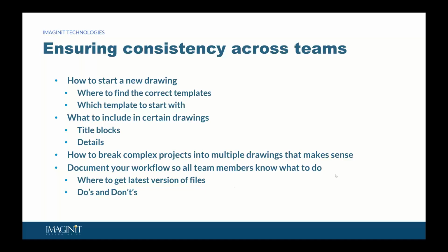And some of the other do's and don'ts. If you are creating complex surfaces, are you going to be data referencing them into other pieces? If you create a surface from an XML, you can't delete the XML file because the surface will no longer rebuild. If you're using data shortcuts, again, this comes back to the first one. Make sure your file directory structure supports the data shortcuts well. If it's too deep in a file structure or your file paths end up being too long, you're going to run into a lot of problems with that.